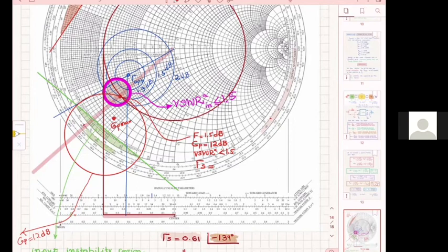If you go lower gain than the lowest possible, you're failing the design. So I'm going to look at where these two intersect. If they don't intersect at all, then I cannot solve the problem. If they do intersect and they have a good overlap, then probably I can do better than 1 dB noise and 10 dB gain. I can go a little less than 1 dB noise. I can go a little higher than 10 dB.